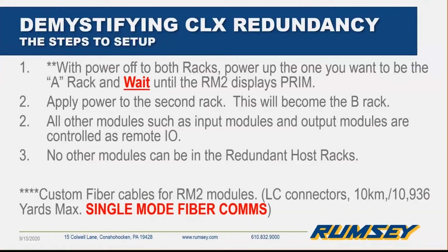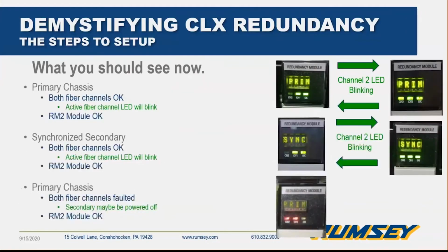Now, some people, which I'm very thrilled to hear, call me saying, I want to have the primary and secondary in the same cabinet. That's okay. You can separate them and you can make your own fiber cables. The Rockwell ones go up to 30 meters. Maybe those are long enough, but you can make up your own. One biggie here is LC connectors are the same, but they are single mode. Those of you who know fiber connectors and other devices, the switches, most of the time it's multi-mode. These need single mode connections.